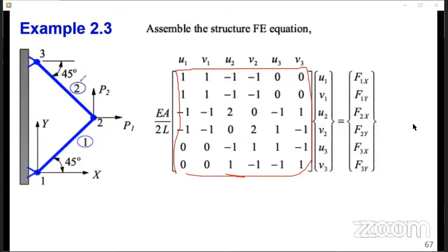Now, once you reach this stage, you have the global finite element equation. Nothing much now remains here. Just follow the procedures that we are following. Bring in the boundary conditions, reduce your equations, solve for the nodal unknowns, and any other derived quantity that is required. So what do you know so far about the boundary condition? We want to define the boundary value problem.